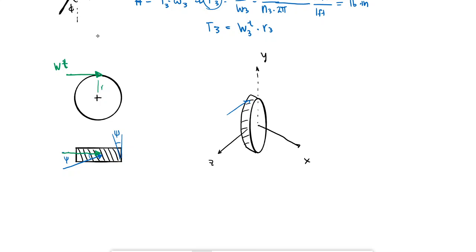Okay, the component of the actual force that is on the plane of the screen, meaning that there's another one that goes in the axial direction, because it's the axis of the gear. Okay, so this would be WA and this would be WT, right? So actually this would be the green one, and this would be the red one. Okay, like I said before, it's not just a point load because it's distributed on the teeth.